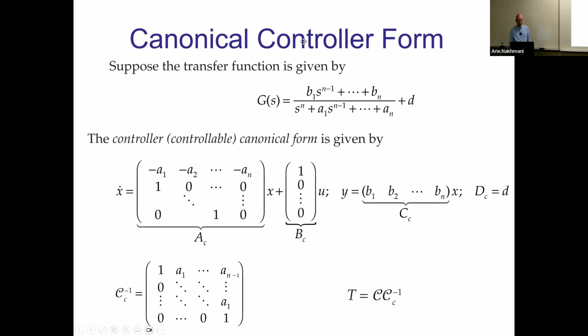That transform to that particular state from any other state will look like that. It will be the controllability matrix of your original state, which is your original matrices A and B, okay? Times that particular matrix. This will be that transform that we talked about, the similarity transform, to that particular state. So it will take you from any given controllable state to that particular canonical state. All right, that type of transform. Questions so far?